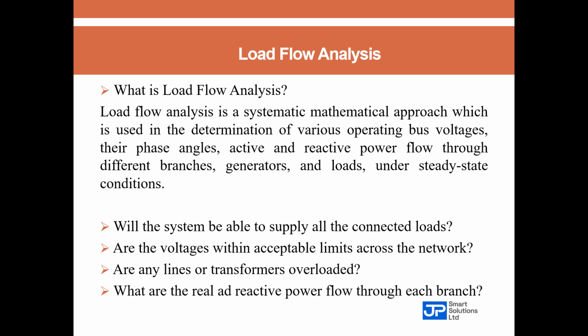Now, can you guess the problem? The transformer feeding that part of the building was already overloaded at 110% of its rated capacity. That was the problem, transformer overload. Now, the solution was simple.